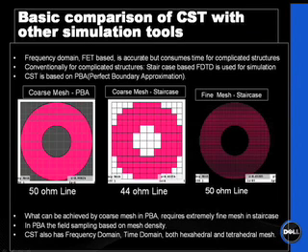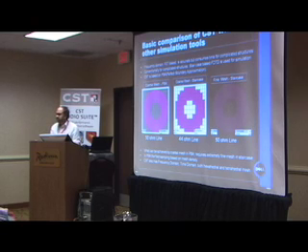Here, just to give a very brief comparison of the CST method with the other simulation tools. Frequency domain methods like HFSS, based on FEM, finite element theory, are fairly accurate, and give very nice results. But as the parts increase and the structures become very complicated with a lot of curvatures, it becomes very time consuming because we have to solve each and every tetrahedral mesh cell.